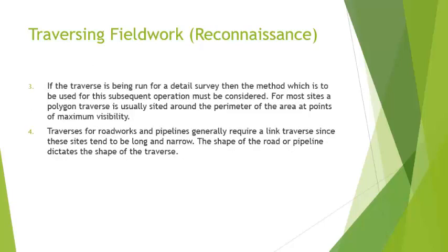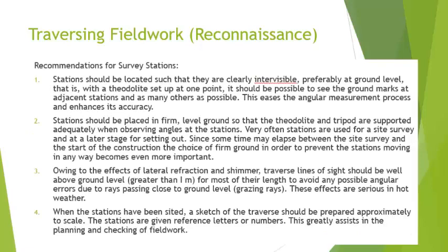If the traverse is for a detailed survey, maximum visibility is highly preferred. Always the maximum visibility. And for roads or pipelines, a deep understanding of the design plan is crucial. It's very crucial, especially regarding the orientation of the traverse.